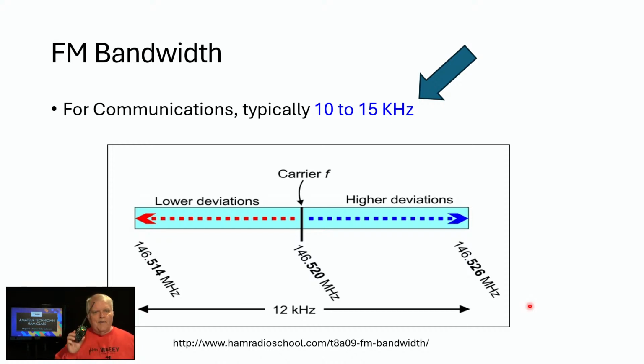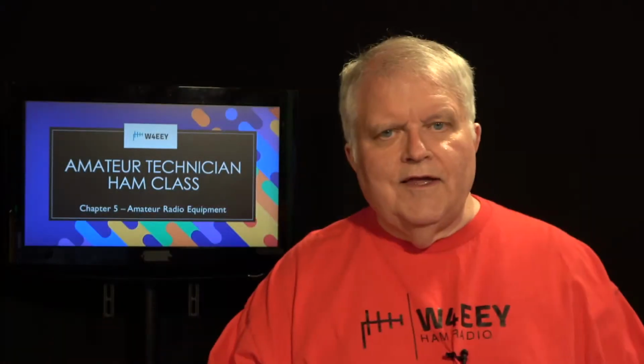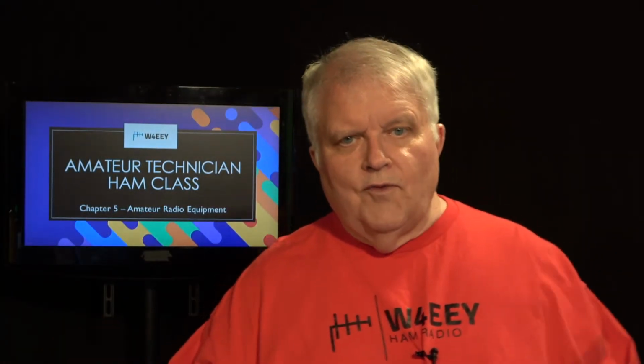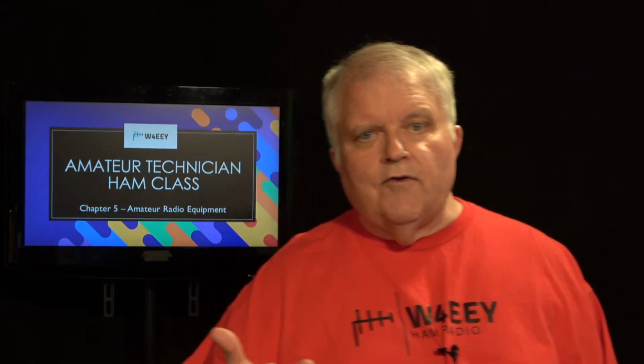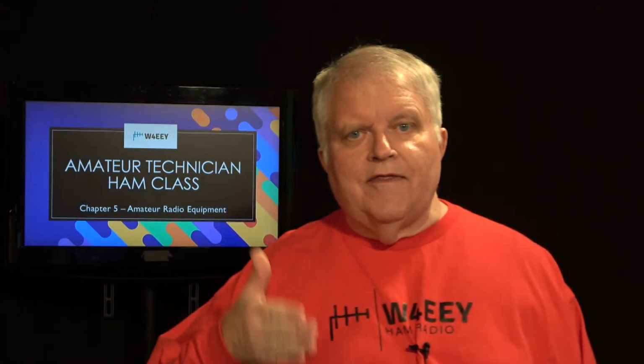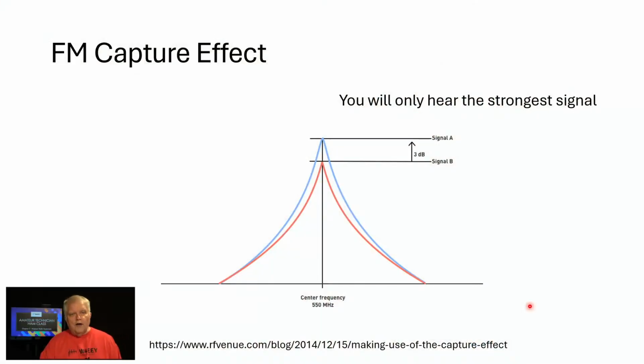An interesting phenomenon with these FM radios is that the receivers inside will capture the strongest signal. So if there are two signals that are transmitting on the same frequency at the same time using FM, only the strongest signal is received because of something called the capture effect in the demodulator in the radio. So just something to be aware of.